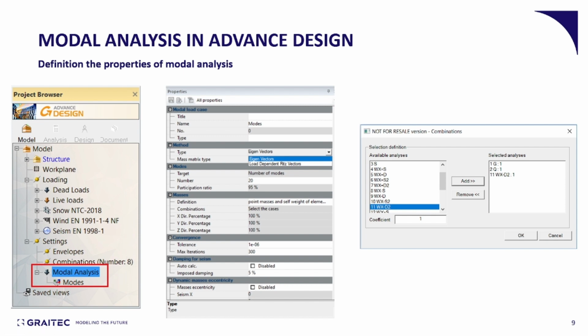combination of the dead loads and the live loads we explained earlier in the definition of masses. Here the user can define which loads will be taken into consideration when defining the masses. It is basically to explain that when a seismic load is applied in a structure, the user can define if those dead loads are going to vibrate with the structure or not.